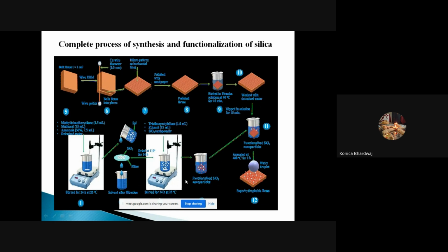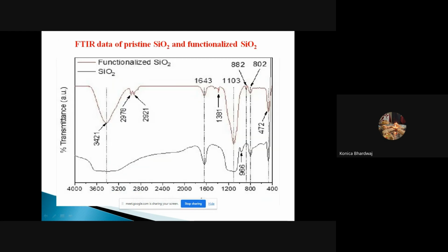And after preparing the coating, we have prepared the surface, that is metal and alloy surface. Preparing surface means we have etched the surface to make it compatible for the coating, and then we dip the brass and copper surface in that synthesized coating and achieve the superhydrophobic surface as required according to the analysis.